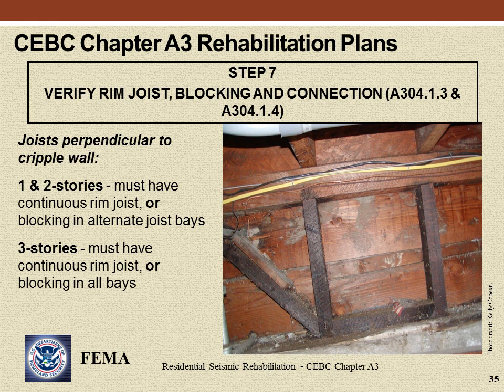Step 7 addresses the connection between the floor framing and the cripple wall top plates, where a cripple wall is present, or foundation sill plate, where cripple walls are not present. Where floor joists are perpendicular to the foundation, this involves two considerations. First, the presence of rim joists or blocking within the floor depth, and second, the fastening from the rim joist or blocking to the top plates or foundation sill plate.